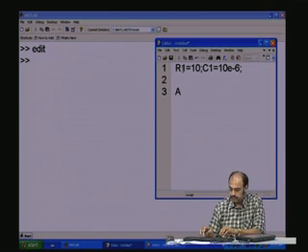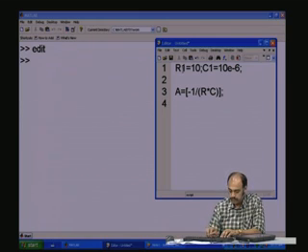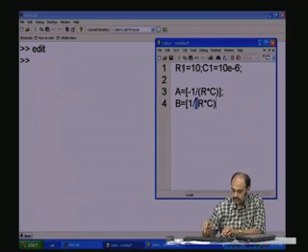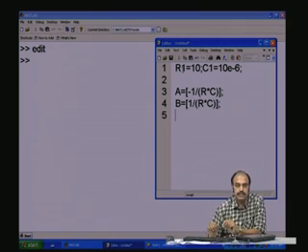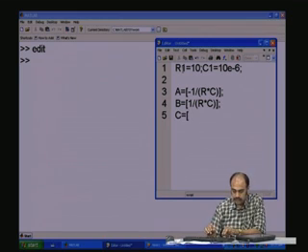Now, the A matrix is given by minus 1 by R into C. We saw this in the earlier session also. B matrix equals 1 by R into C. Now, if we want to see the output voltage as Vc, then we give the C matrix equals 1 and the D matrix equals 0.